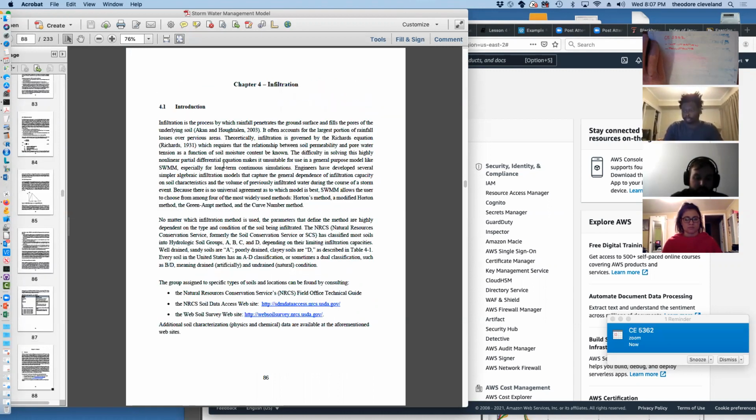The other way our computer program generates runoff is by computing infiltration and the volume of water that's left over in a computational time step, one of our delta T's, if you will, after that infiltration is what becomes available for runoff.